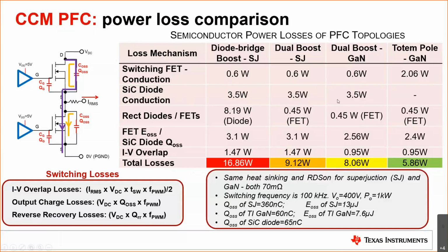So if you add those two and compare them with the 2 watts of the losses in the totem pole, this is actually also already a deduction of 1.5 watt. Then the same counts again for the rectification. It will massively decrease versus the full bridge rectifiers from the previous dual diode bridge boost. And yeah, the other losses will then again moderately decrease versus the previous designs.